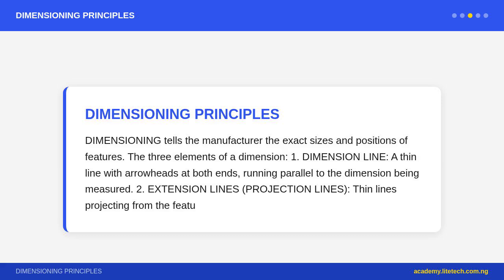General rules for dimensioning. 1. Every dimension needed to manufacture or inspect a part must be shown, no guessing or calculating. 2. Do not duplicate dimensions, show each dimension once only. 3. Dimension lines should not cross each other unnecessarily. 4. Extension lines should not cross dimension lines if avoidable.